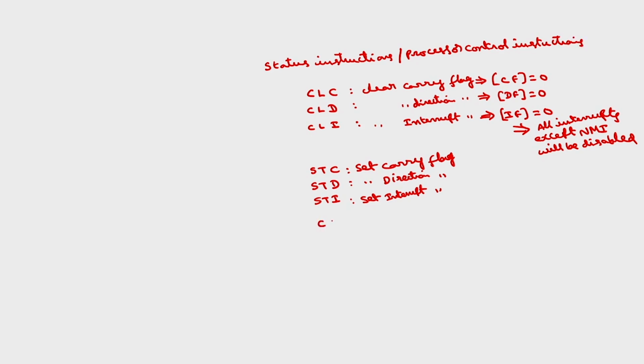And we have one more instruction related to this one. This is complement carry, CMC. As the name implies, the contents of the carry flag will be complemented. If it is set, after this it will be reset. If previously the carry flag is reset, and I execute CMC, then the carry flag will be set. It simply complements the carry.